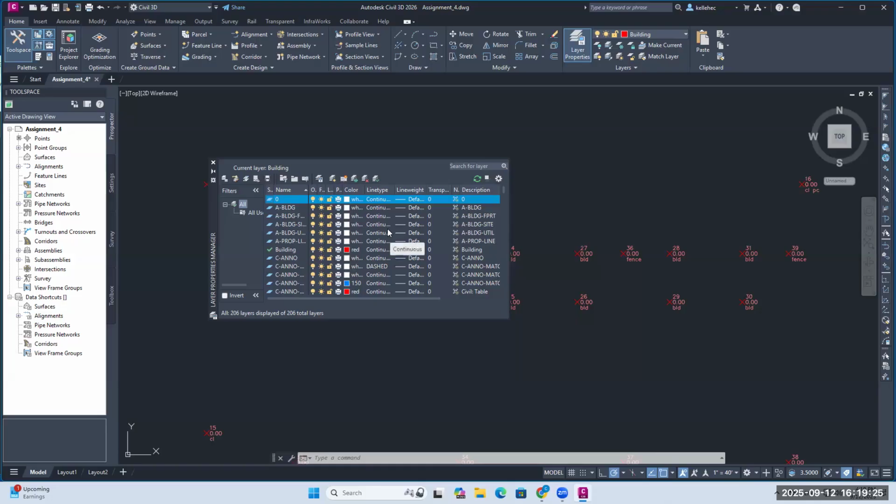A lot of the land development drawings that you will see in this class and outside this class have a lot of information associated with them. So when you are drawing something, it is helpful to have different layers because you can turn those layers on or off. So over here, if I hover, what do you think that light bulb does? It is an on-off feature to turn a layer on or off. We have some other features here that we'll also use later in the course. You can lock a layer, meaning you won't modify it, which is sometimes quite helpful.